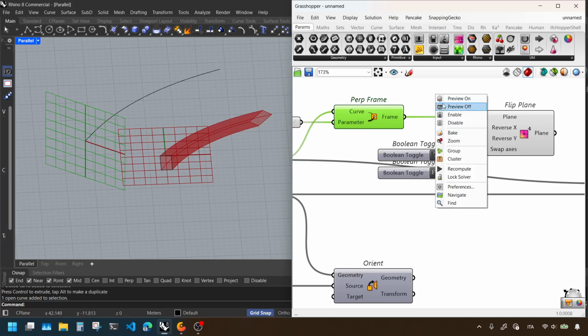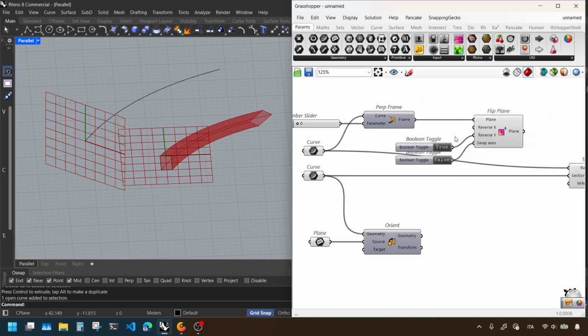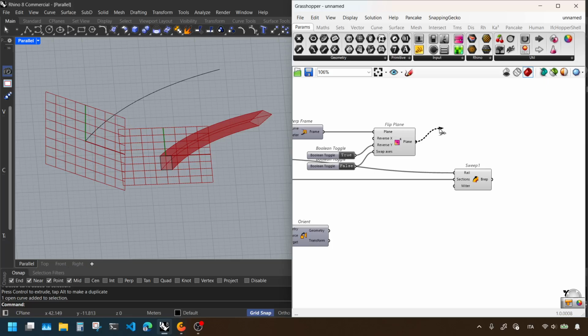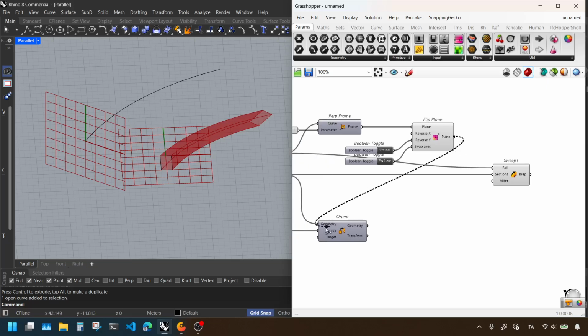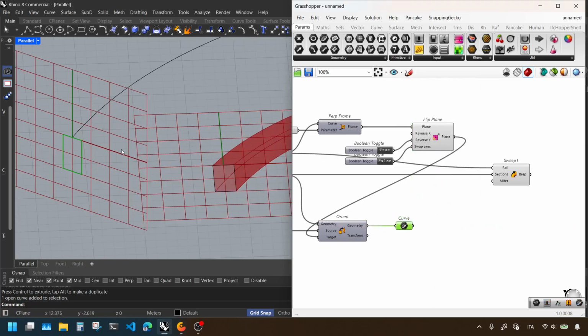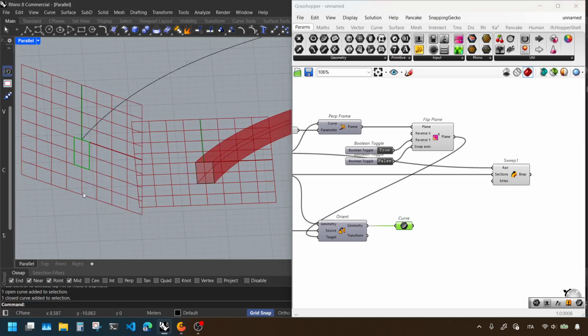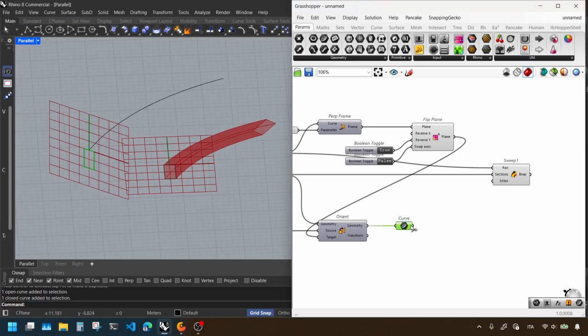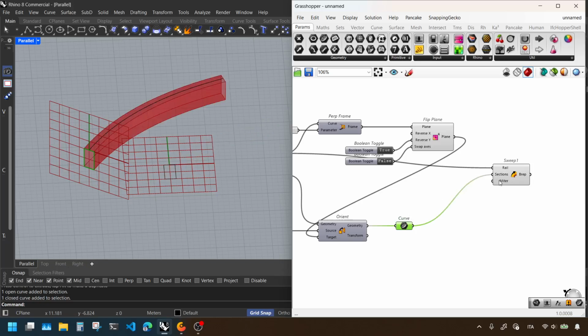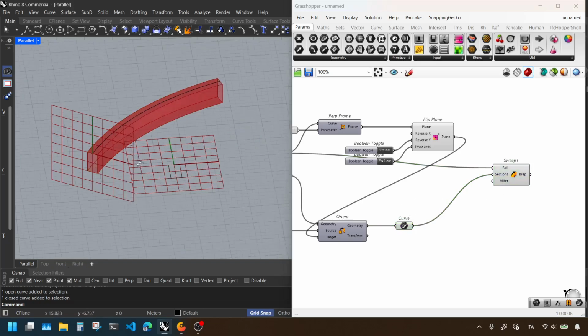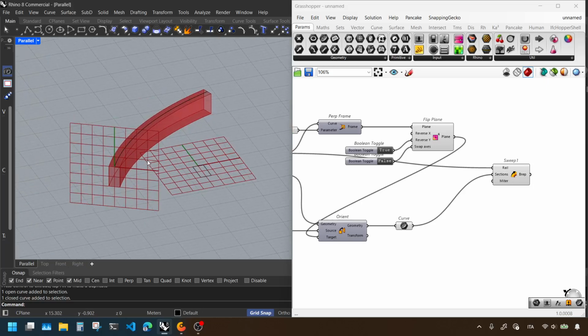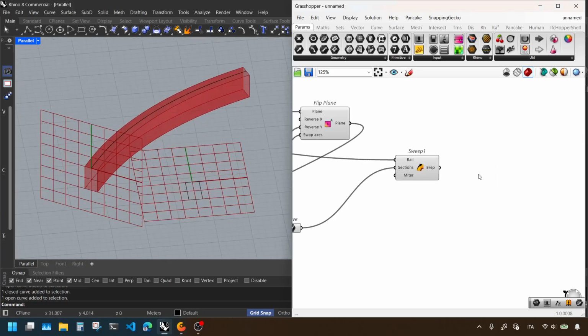And then if you hide this one, you see how it's correct. And then you can take this one and put it into the target. And indeed, now if you inspect this geometry, you'll see that it moves this curve to the start of the rail. And then you can take this one, put it to sections, and indeed we get the correct sweep we were expecting from